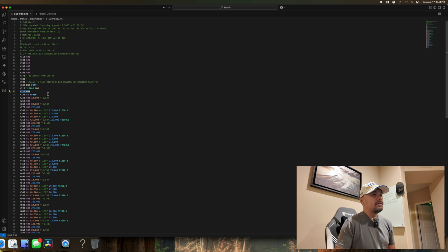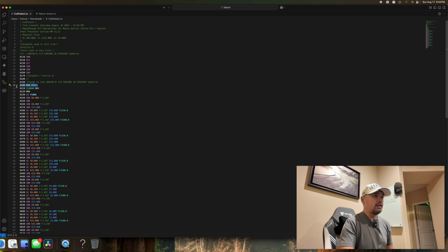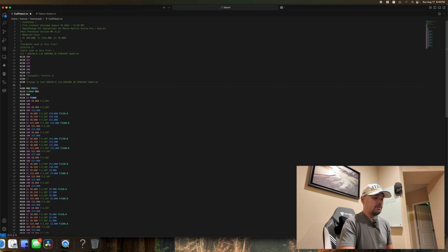But if you notice, at the beginning of the tool change, it doesn't retract the AutoDustBoot. Normally there should be an M9 here, so let's just add an M9. Every time we see M98, there should be an M9 in here.